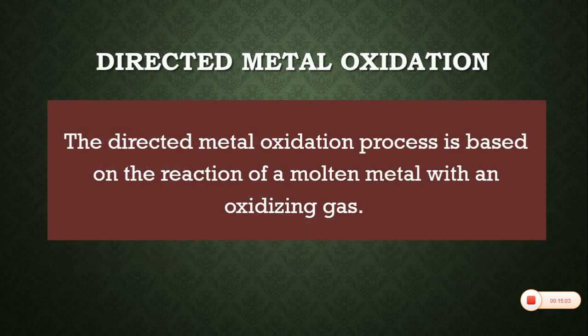Now, we move on to the next gas phase reaction method, which is the directed metal oxidation method. It involves the reaction between a gas and a liquid. A reaction between a gas and a liquid is generally impracticable for the production of ceramic bodies, because the reaction product usually forms a solid protective coating which separates the reactants and effectively stops the reaction.